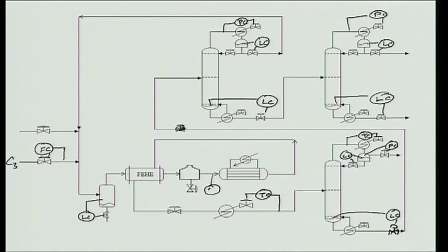Yeah, the conventional thing to do. Why did I put in the furnace there? It was put to control the temperature of the reactor feed. So, that is what I do using this. Of course, what do I do with this valve? Of course, I shall set the cooling rate such that temperature of the shell is maintained constant at whatever was its near optimum value over the entire throughput range, which was I think 367 degrees Celsius or something like that. Okay. Then what do I use this valve for? Well, this valve will be used for keeping the pressure of the reaction section.